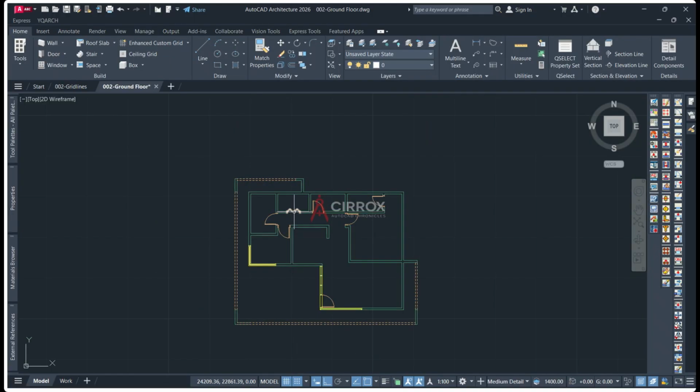So we can now go ahead and add in our windows. So to add in our windows, the same process. We are going to go back to the palettes, this time windows, blinder, and properties. Now change it to, I'll make it 15 by 15. Alright, the sizes in here are all standard sizes that we are actually using, so it's not going to be a problem in here. And so 15 by 15.